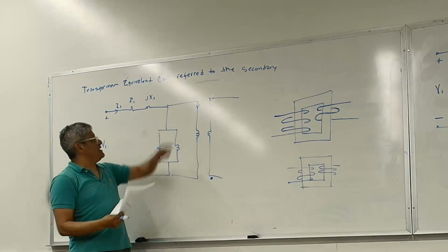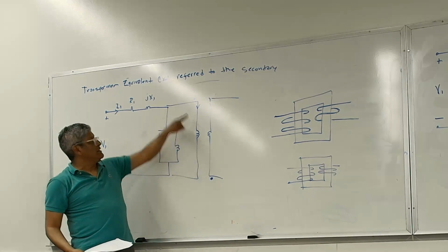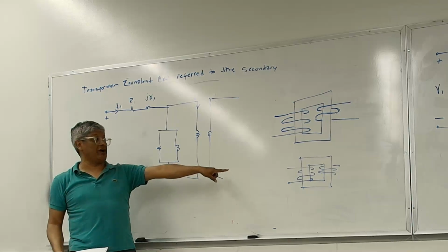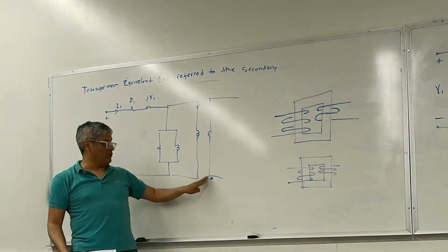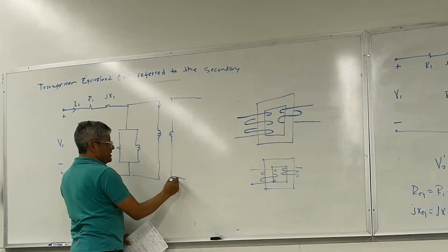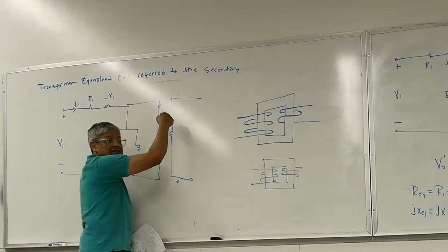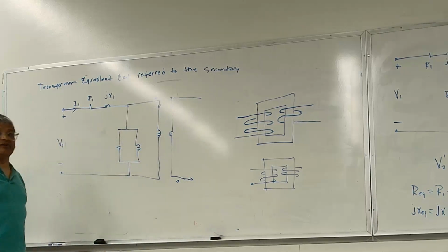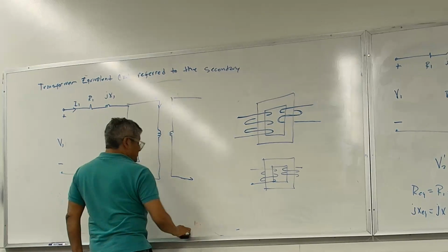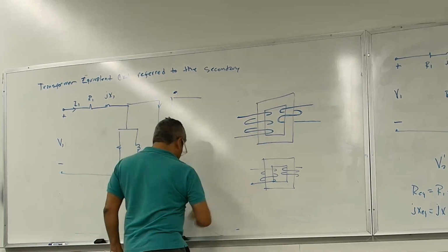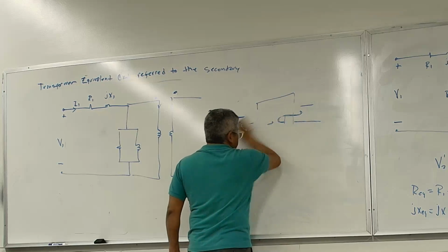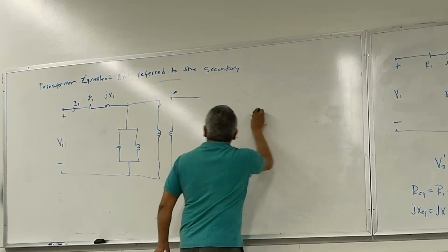So if you see this here, that means that's the transformer polarity, and that is a big deal. We'll talk about it when we talk about three-phase transformers, okay? Because the current here is going to induce a current in this direction with a different phase angle. So that's what that means. If you see those two dots, that means that this is how the transformer is built, and that's probably 95% of the time how we want it.